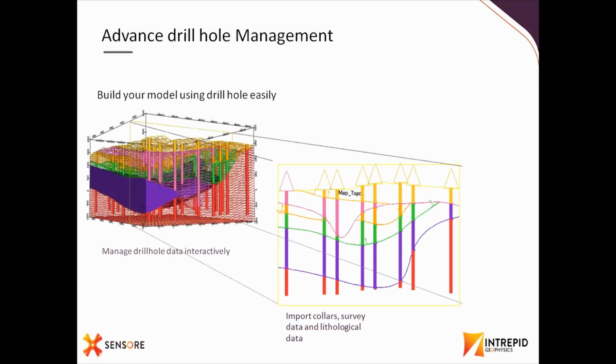A drill hole management system is available in GeoModeller, where we can import the drill hole data along with the lithology, so that GeoModeller can understand the layer information directly from the well and do the interpolation accordingly. You can see from this cross-sectional slide, all the intersection points of the wells are automatically interpolated by GeoModeller. We don't have to digitize everywhere, just provide some limited data and it will do the interpolation by itself.